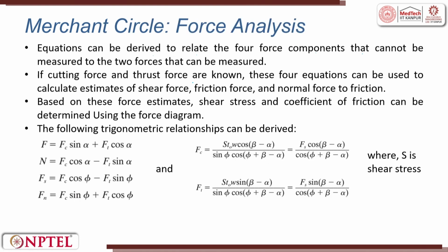So, if the cutting force and the thrust force are known by some dynamometer, these 4 equations can be used to estimate the shear force, friction force, and normal to friction force. Based upon the force estimates, the shear stress and the coefficient of friction can be calculated using this force diagram. Using trigonometry, we will try to figure out the relationship between F, N, Fs, Fn with respect to Fc and Ft. So, F is equal to Fc sin alpha plus Ft cos alpha. You can try to solve it. If you have difficulty, we will see it in the tutorial.